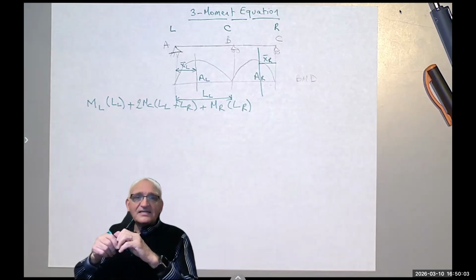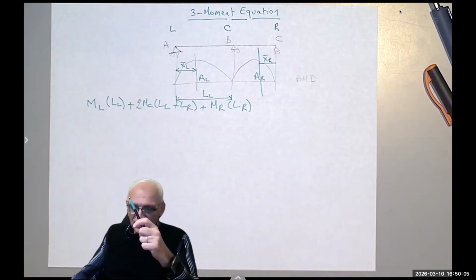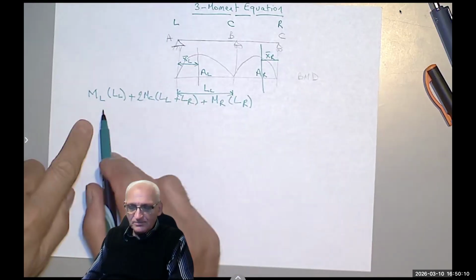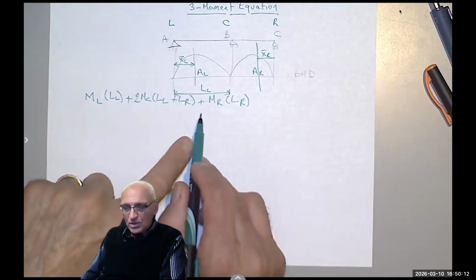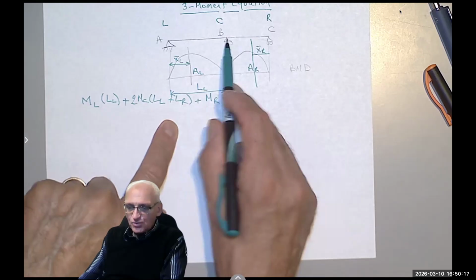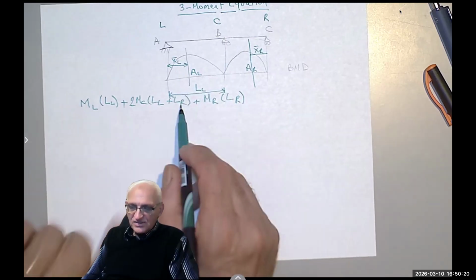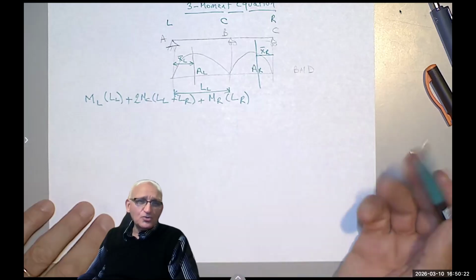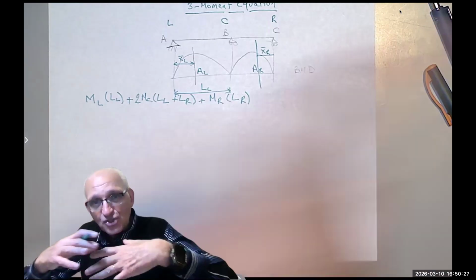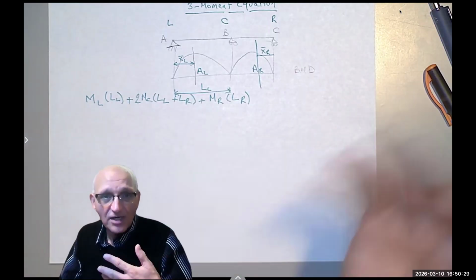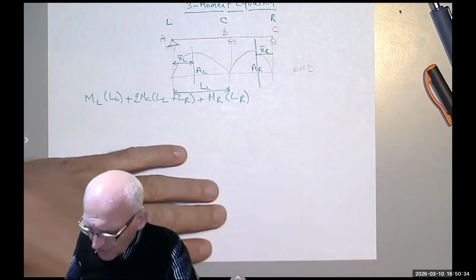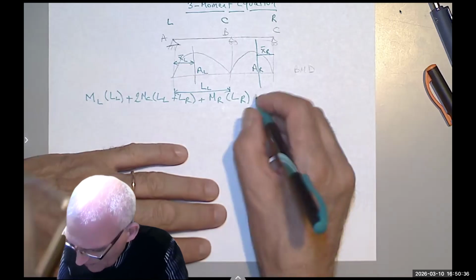And even if that's so, instead of dividing by E and 2E, we are going to divide this part by 1, this part by 2. If this part of the beam has an E twice as the left, then every time I have L right, I divide it by 2, right? It's the same thing for I. I can get a ratio of I left to I right and simply divide by that ratio. We are not going to see that in most problems.